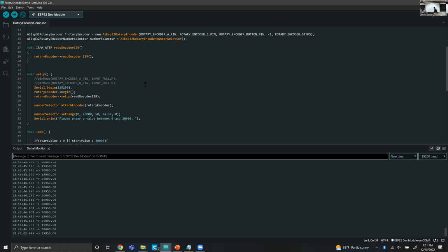Because the user can, this is the desired value from the user input. What happens in your system is your control loop doesn't have to do anything with them. Then you can't tell them now to rotate one more degree. It was 2,500, but for any loss or anything, it's 2,485. There's error, right? So you have to make sure the encoder keeps sending back the error until the PWM has to increase until it reaches. That's the feedback that you need.